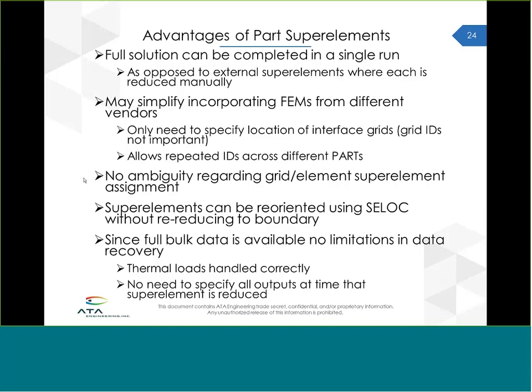And then with part superelements, if you have the full FEM, you could do any data recovery you want. With an external superelement, you have to decide up front, what outputs am I concerned with? Because you create those data recovery matrices when you create the reduction. If you have the full FEM in a part superelement, you can change that from one run to the next. You could decide you want to look at element forces on one run and displacements on another, because, again, all the detailed FEM is still there.